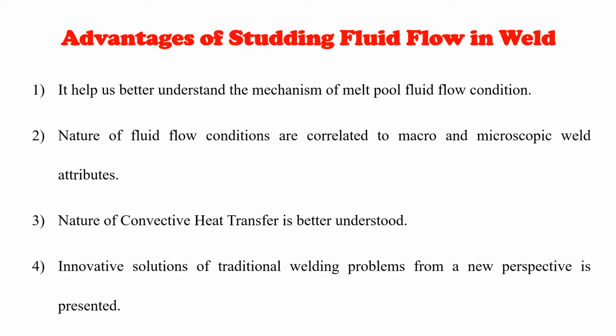It helps us better understand the mechanism of melt pool fluid flow condition. The nature of fluid flow is correlated to the macro and microscopic weld attributes. The nature of convective heat transfer is better understood, and innovative solutions of traditional welding problems from the perspective of fluid dynamics are presented here.